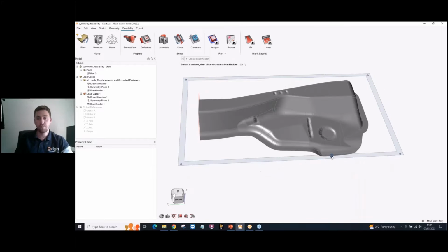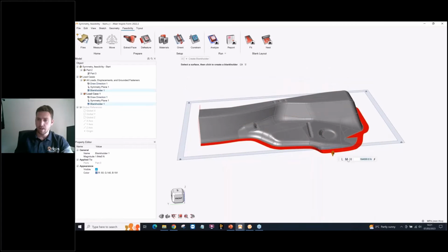At this stage, we can modify our forces. So if I click on it, here we can modify our forces for our machines. So I'll set this to low, for example, and we can type in any forces here. Again, another important step: we don't want to be setting forces that our machines can't produce. But here, you can set this to low, medium, or high, or put in your custom settings. So I'll accept that, and then I'll just do one more.